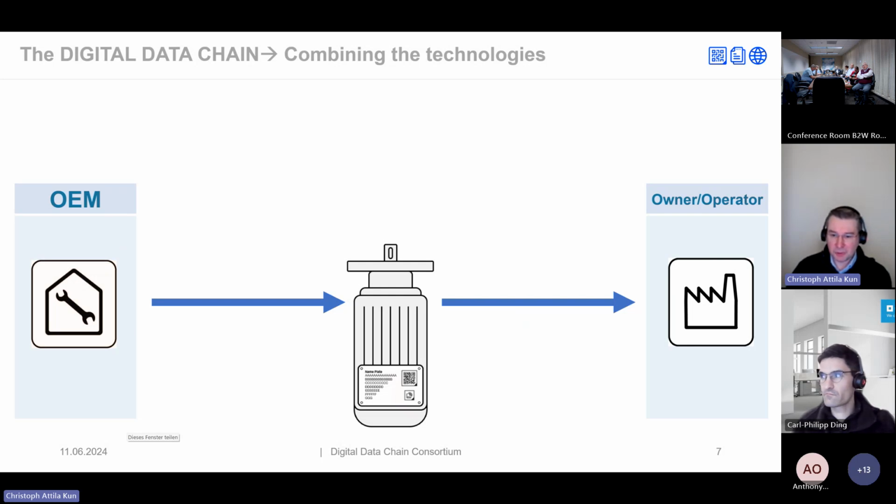The first thing that you have to do is to globally uniquely identify the equipment to be able to assign information to it unambiguously. And therefore, we developed together with many partners, also including Flowserve and Amazon, but also companies from all around the world, the IEC 61406 identification link. So you see here a QR code with a frame and a black triangle and also an RFID tag. That is basically what we standardized across the industry, and this identifier is based on a web domain.